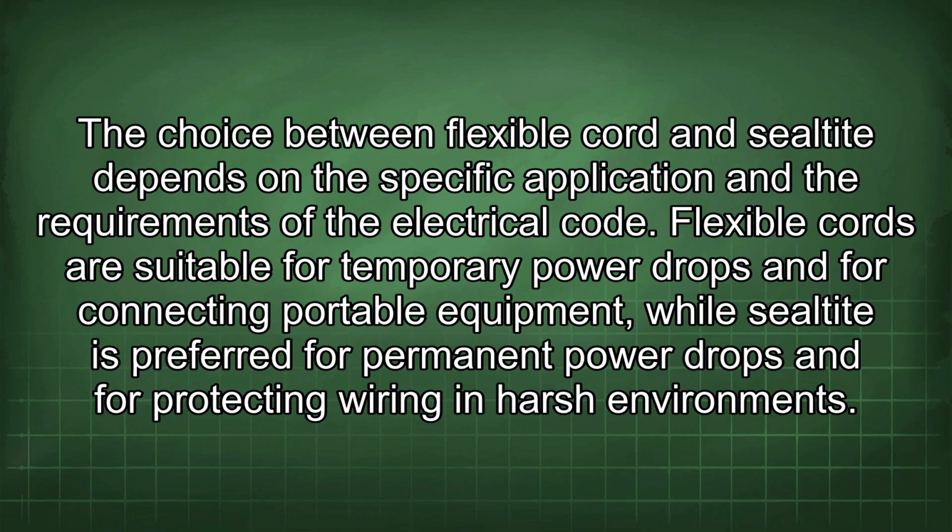The choice between flexible cord and Sealtite depends on the specific application and the requirements of the electrical code. Flexible cords are suitable for temporary power drops and for connecting portable equipment, while Sealtite is preferred for permanent power drops and for protecting wiring in harsh environments.